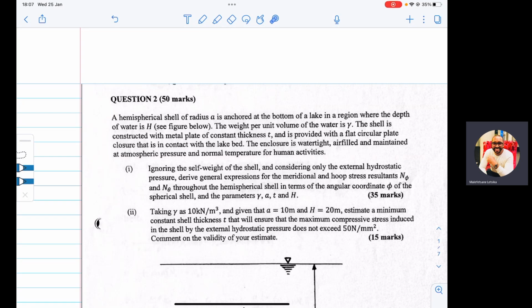If you remember with the analysis of plates, we assume that plates resist the transverse loading applied to them by bending. Hence, if you look at flat slabs, we are interested in that bending, to see also if the deflection is too much, the maximum deflection, what is it, etc. Whereas shells resist those transverse loadings through the internal actions that act in the tangential plane.